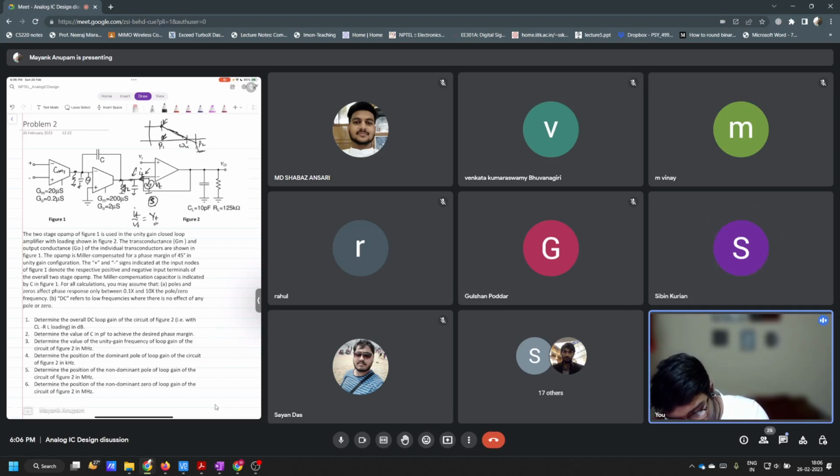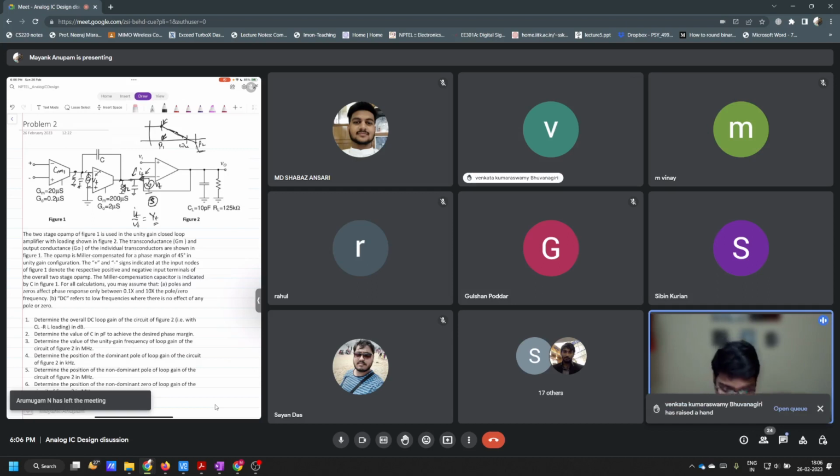Similarly, you do the same thing here also. You give VT here and you measure the current coming out of it, and you find the admittance here also, and they will both have imaginary and real components. What does the imaginary component in admittance mean? It is basically due to the capacitance. See what is the value of that capacitance and what is the value of the real term. That will correspond to a conductance or a resistor. And you find out what the pole location is because of that.